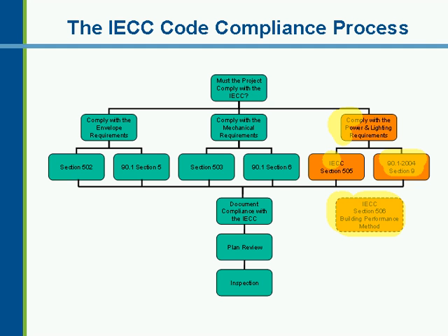And then you input the requirements or the design for your building, the way it's going to be designed and built. And if your energy use is at least as low as the base building, then you comply with the code. Of course, this is a more complicated system, requires a lot of modeling inputs and a lot more work and generally a lot more expense. And it's usually not done this way unless there are some reasons why you can't comply prescriptively. And usually this is only limited to larger, more complicated structures or ones that have an unusual system of heating and cooling, for example, might be a reason to do that.